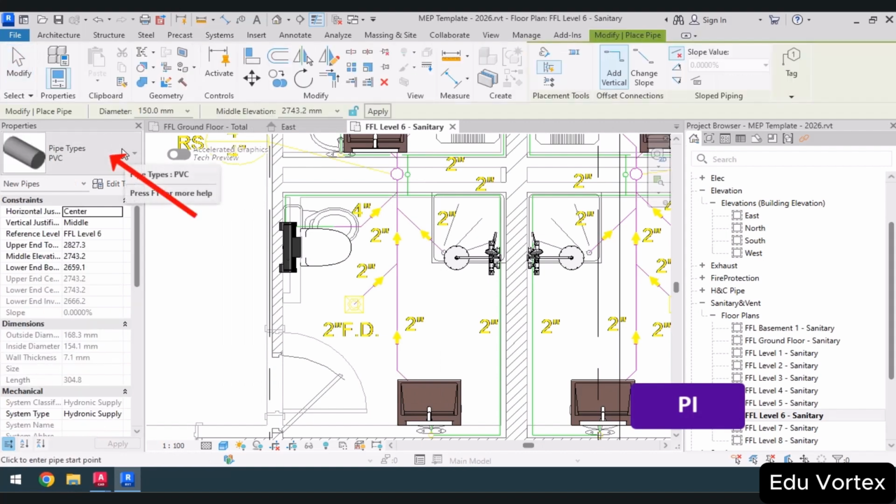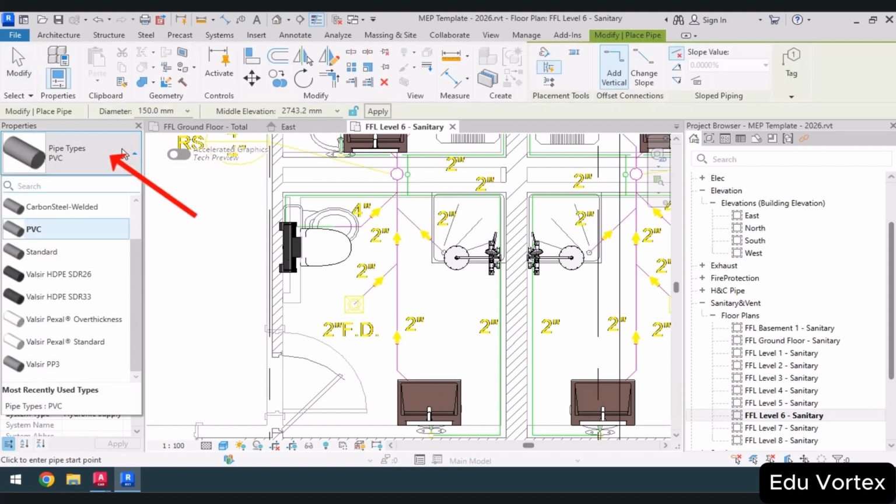In the properties window, I need to select the material and type of connections for the wastewater pipes. Drawings should specify what material the pipes are made of. We want to use polypropylene. The brand mentioned in the beginning is an Italian brand that provides us with families of pipes and fittings.